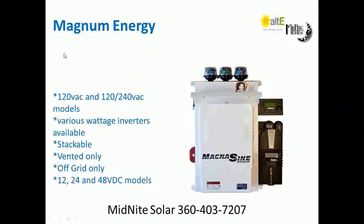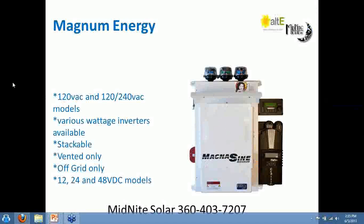Okay, yeah, Kim is asking me to explain why in AC coupled you need a critical loads panel. What I mean by that is if you don't have any renewable energy on site right now, you've got one main panel where your utility comes in with all your circuit breakers in it. And if you want to do backup, you need to break the loads out that you want to back up, i.e. critical loads.